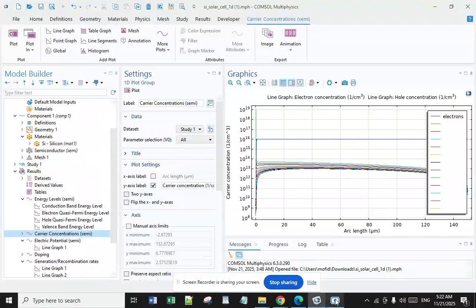In order to protect the cell against the effects of the outer environment during its operation, a glass sheet or another type of transparent encapsulant is attached to both sides of the cell. In the case of thin-film solar cells, the layers that constitute the cell are deposited on a substrate carrier. When the processing temperature during the deposition of the layers is low, a wide range of low-cost substrates such as glass sheet, metal, or polymer foil can be used.